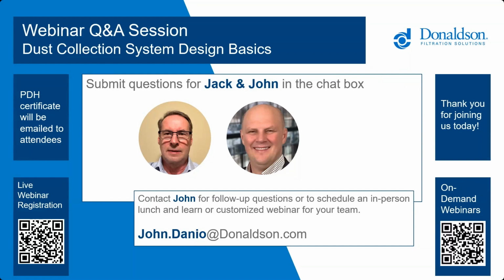Probably the one thing that we are looking at and can consider is our trusted ductilator, right? Which helps you with some sizing. It gives you some guidance on the different velocities that are needed per the different contaminants that are out there. And if there's a way for us to digitize and make that more readily available, I know that there's online ductilators. We have our own ductilators. Those help with airflow calculations.